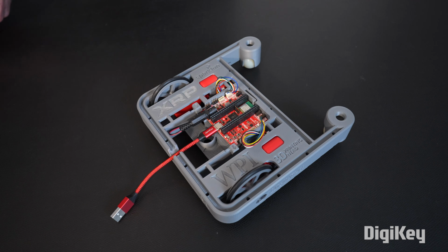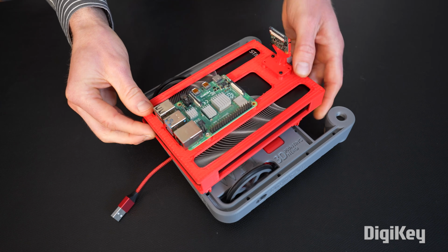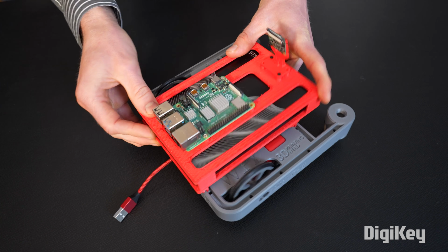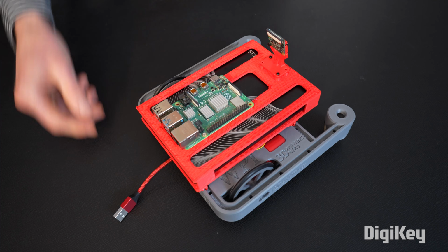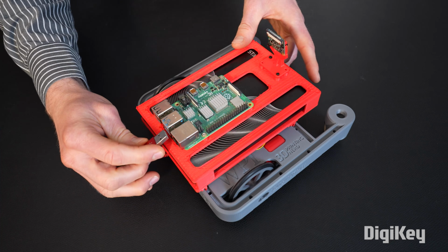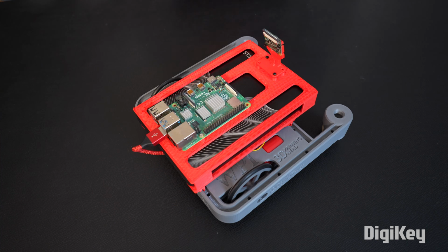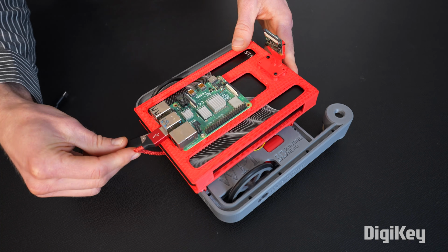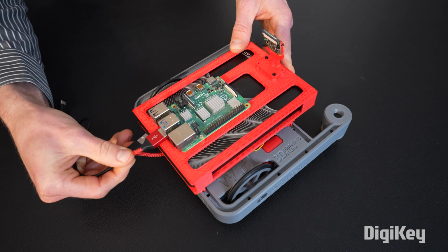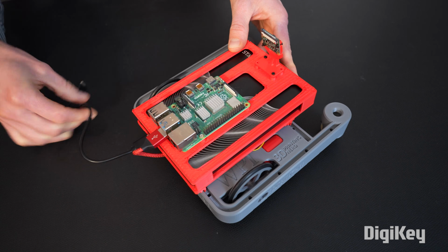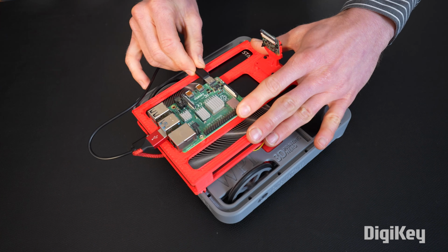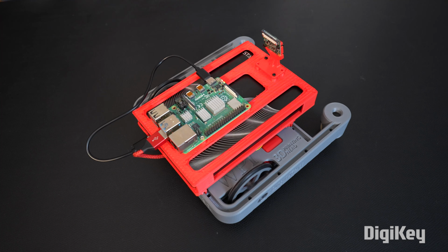We'll add a custom 3D printed cage on top that holds a large power bank and a Raspberry Pi 4B. I put a PiCam 2 on as well for a more advanced demo later. Note that I had issues getting the PiCam 3 to work as it uses a different chip that does not have support in Ubuntu 24 by default. We'll connect the XRP board to the Raspberry Pi and then apply power from the battery.